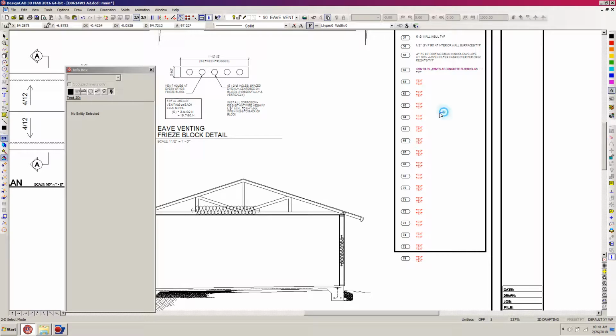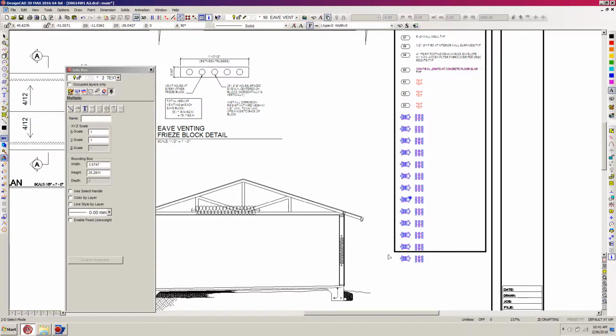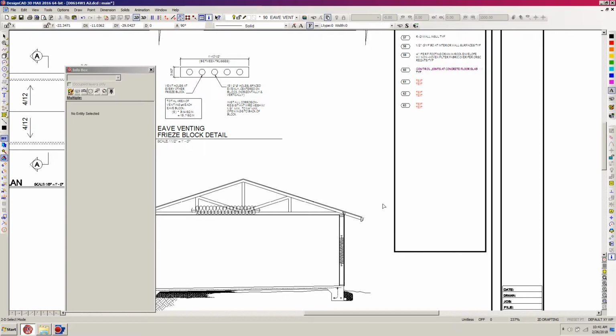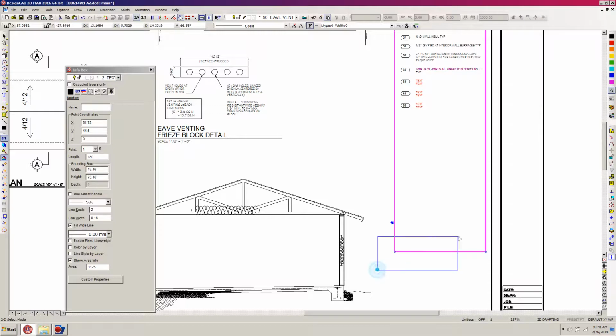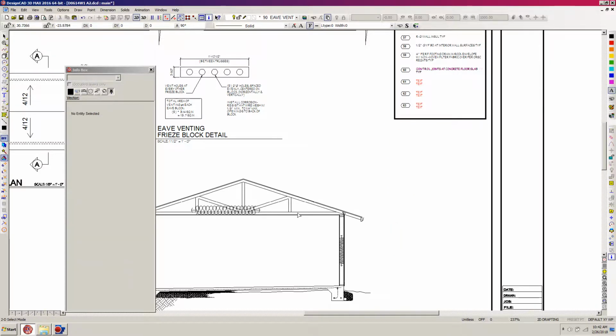But what this is going to do is as I select these, and I'm going to just hit delete, it's going to allow me to scoot my section drawing over a little bit further. I'm going to select this box, and then I'm going to select both of these points. See that they both turn to a dark blue. I'm hitting H to go into orthogonal mode. You can see it up here. Now I'm going to right click on this one point, and it'll grab both of them because they're both dark blue and selected, and just kind of scoot up orthogonally here and just set a point with my left mouse button, hit escape.